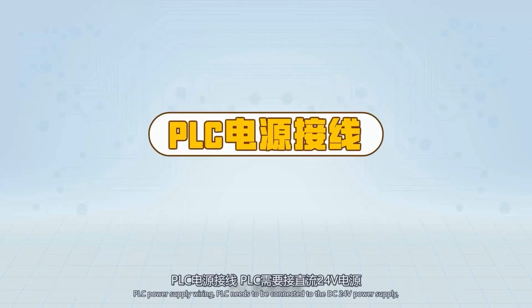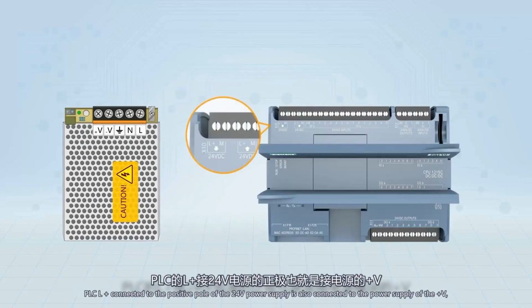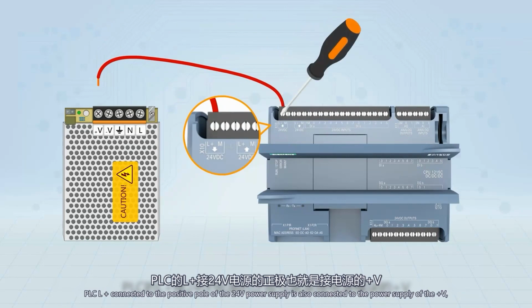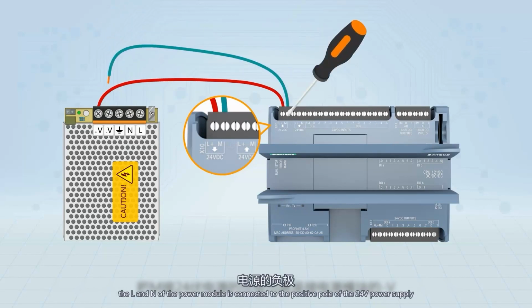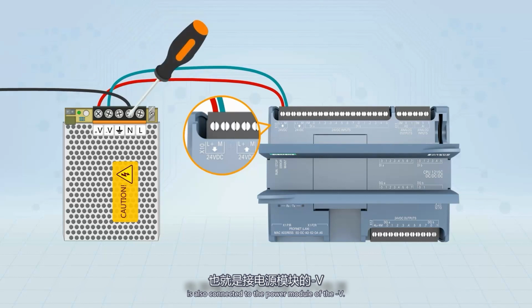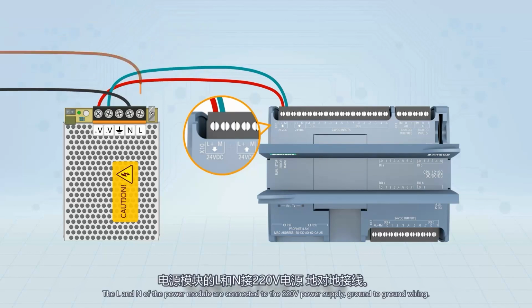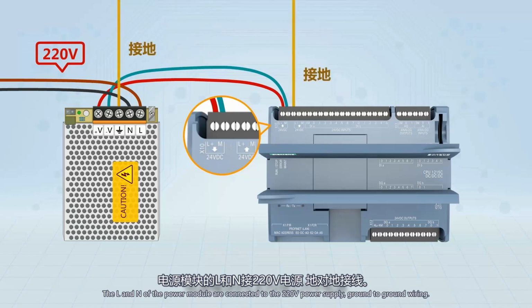PLC power supply wiring. The PLC needs to be connected to the DC 24V power supply. PLC L+ is connected to the positive pole of the 24V power supply, which is also connected to the positive of the power module V+. M is connected to the negative pole of the 24V power supply, which is also connected to the V- of the power module. The L and N of the power module are connected to the 220V power supply, with ground-to-ground wiring.